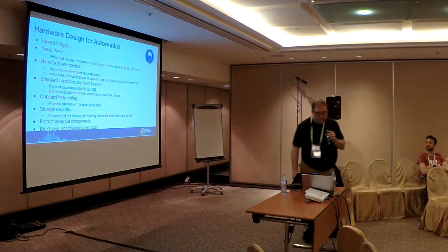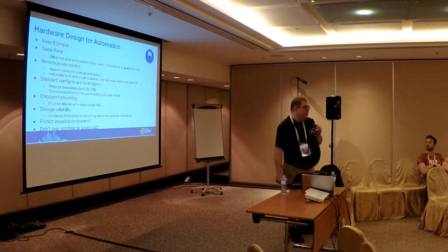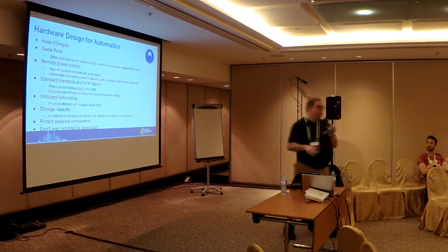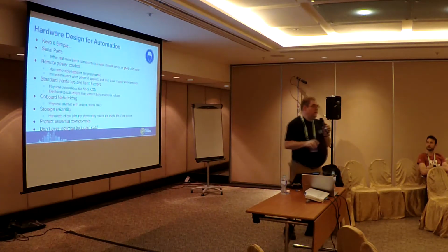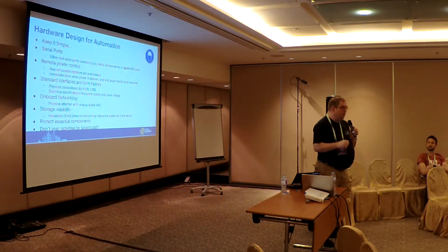Serial ports. Either put real serial ports on, or add good USB serial. And you know what we mean by good USB serial? Stuff that works. Stuff that's unique. And stuff that doesn't go away when you power your board off. Absolutely the right answer for USB serial is to have it be powered by the host, not the device. If it's powered by your device, it goes away.